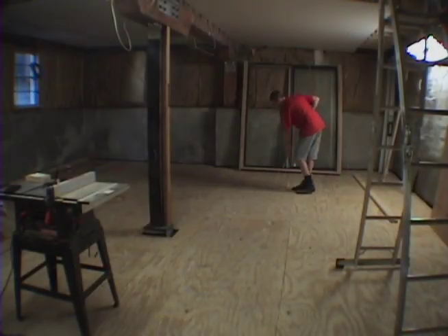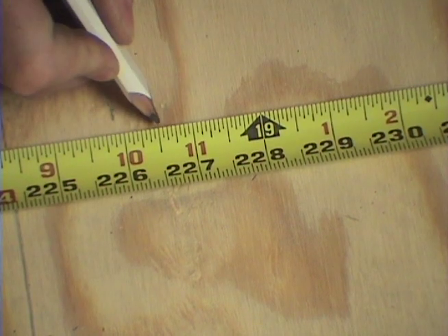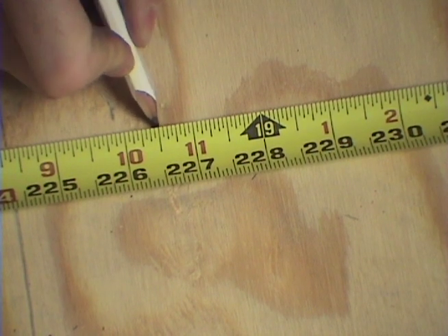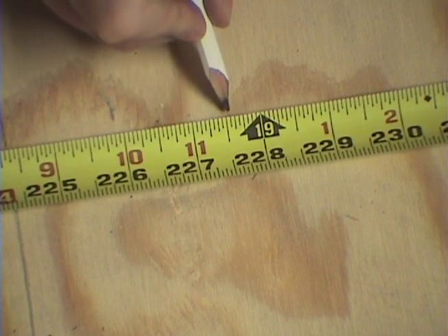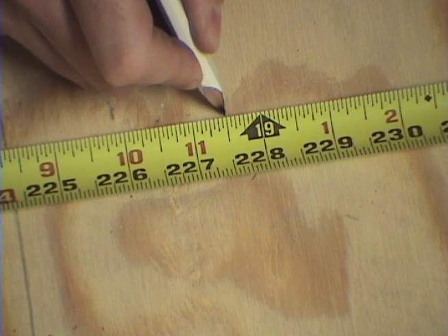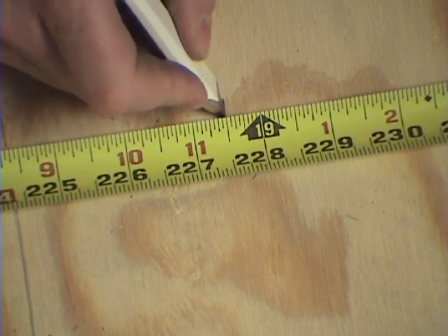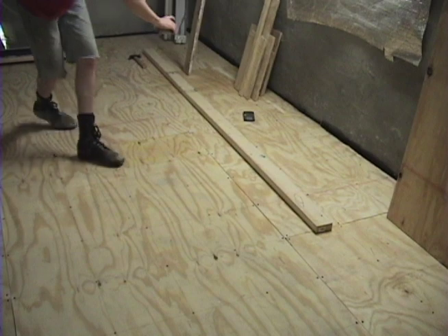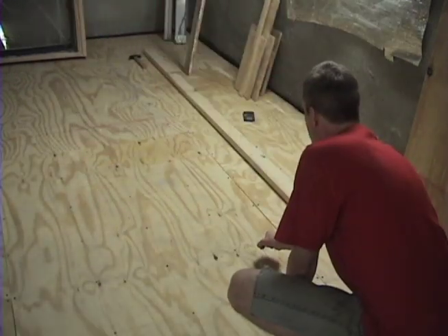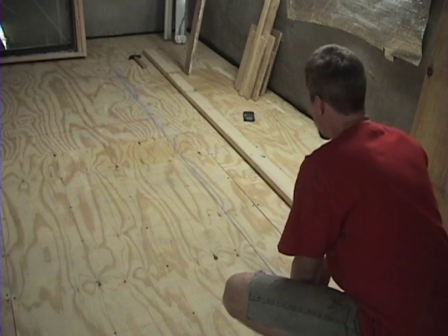The front wall is to be 226.49 inches from the back wall, but we also need to add a 1/2 inch for the drywall on the back wall and another 1/2 inch for the drywall on the front wall. Depending on what thickness of drywall you are using, be sure to account for the thickness at both ends when making your measurements. In my control room design, I decided to mount the drywall directly onto the studs. If you use RC, you need to account for the thickness of the RC as well. So 227.49 is where the bottom plate for the front wall will be. Measure that in 2 locations and snap a chalk line between those as a guide for the installation.